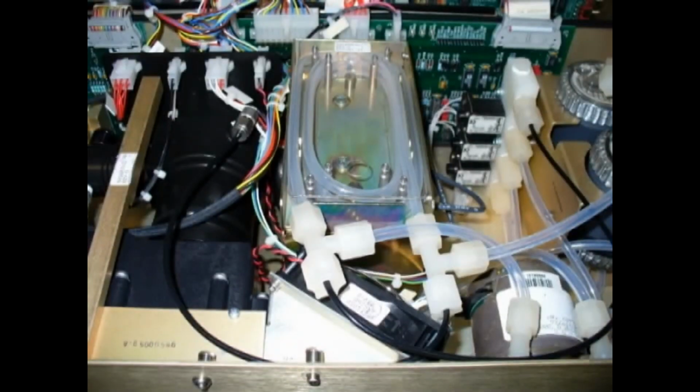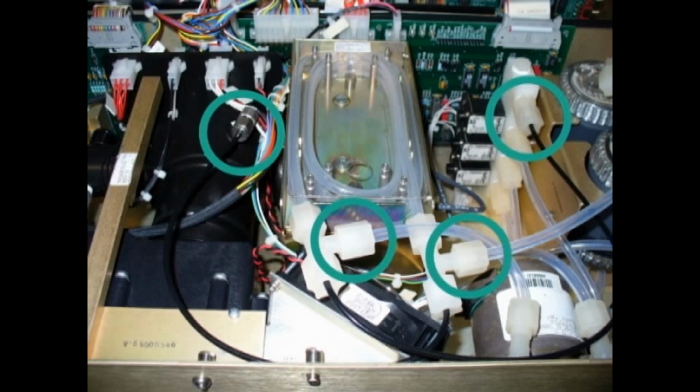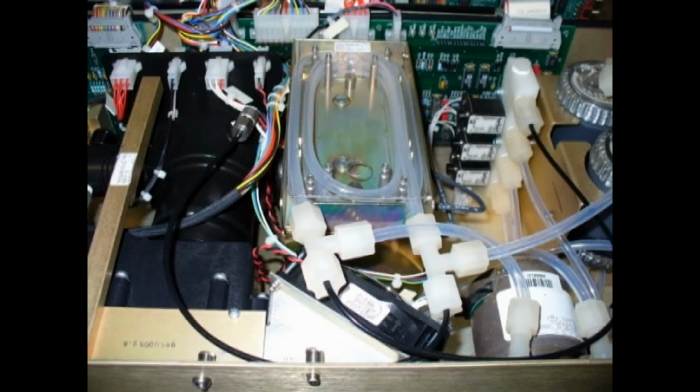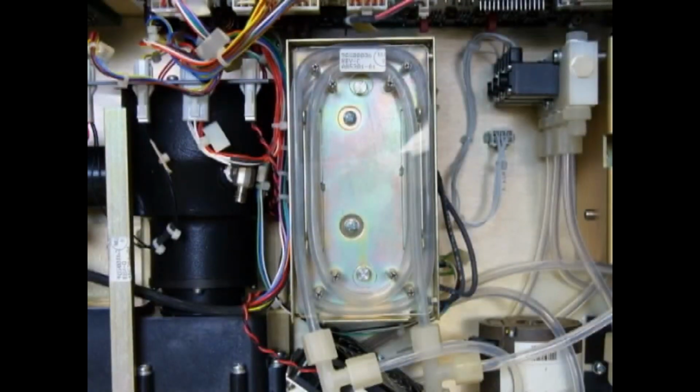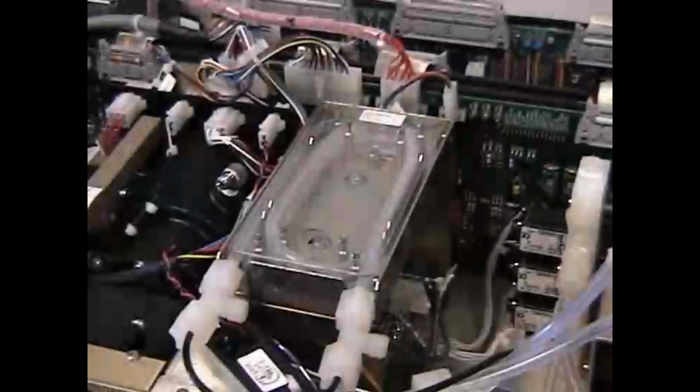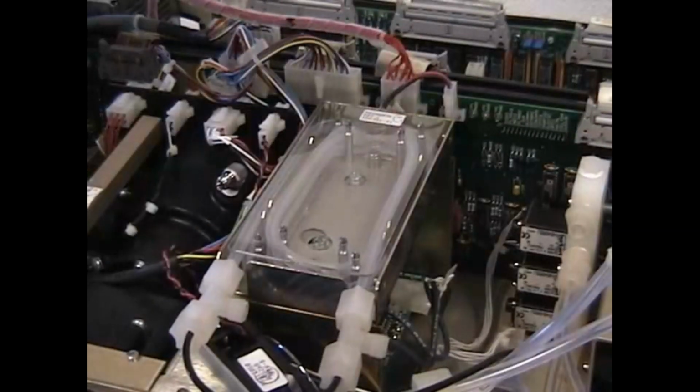To remove the optical bench from the sensor tub, we must first remove the kicker. Take these fittings loose. If you loosen these fittings, you'll permanently damage the kicker. The kicker is held in place by 2 captive screws. Loosen these, remove the assembly, and set it aside in a safe place.